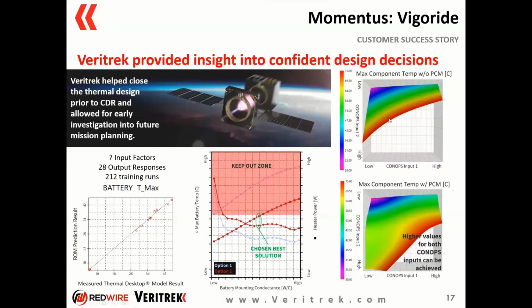So these 2 design comparisons that they did, they were looking at maximum temperature of an onboard component and trying to determine how beneficial it would be if they leveraged some thermal energy storage on board. How much more ConOps or actual operation of their space vehicle could they do if they could keep that component temperature low enough. And so being able to do a direct one-for-one design comparison gave them some insight and information that helped plan future space vehicle design and mission operation parameters.